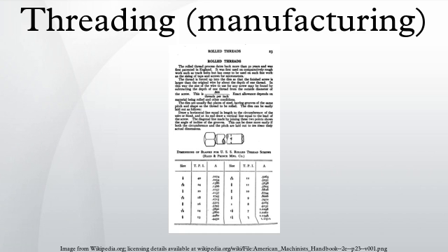Thread grinding is done on a grinding machine using specially dressed grinding wheels matching the shape of the threads. The process is usually used to produce accurate threads or threads in hard materials. A common application is ball screw mechanisms. There are 3 types: center-type grinding with axial feed, center-type end-feed thread grinding, and centerless thread grinding.